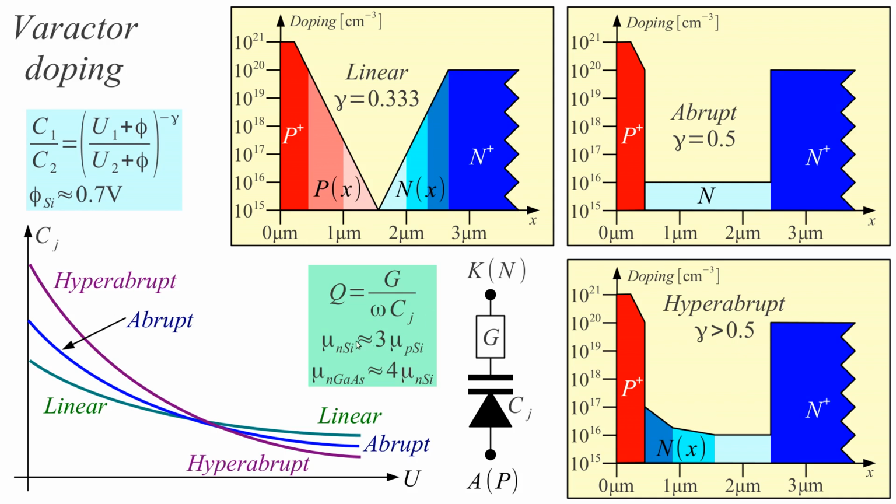First, in silicon, the mobility of electrons is much higher than the mobility of holes. So we would prefer to build our depletion region in the N section, because with N doping the resistance, because of the higher electron mobility, is much smaller than with holes.